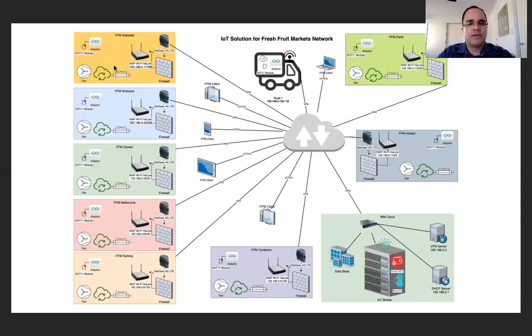The difference here basically will be just the power supply for the Arduinos and the access point. On each site it is from 220 or 230 volts, and in the vehicle, we're going to use the battery of the vehicle, with a voltage of only 12 volts, and just convert to 9 volts to turn on the Arduino, and so on.